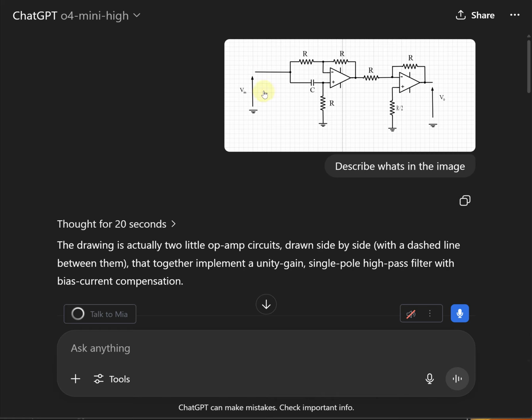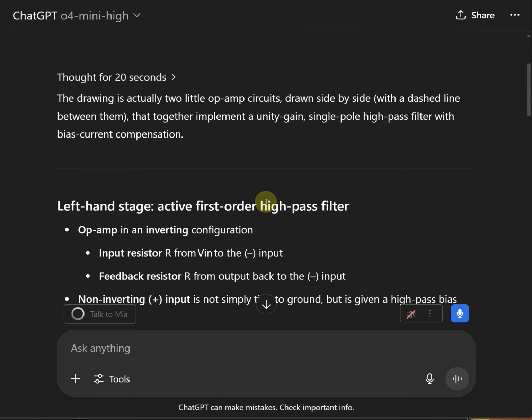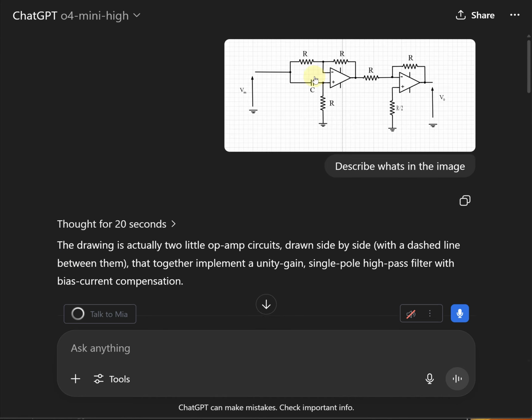And it acts normally, this kind of circuit, as a phase shifter, because it's letting all frequencies through. So in other words, the frequency response is like unity, but the phase shift is not. It goes down negative, and you use it to phase shift sine waves or whatever, particular frequencies. You can't phase shift all the frequencies, just particular frequencies, for a particular amount, that is. So you design it to phase shift a frequency by a certain amount.